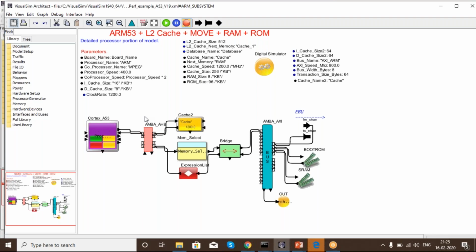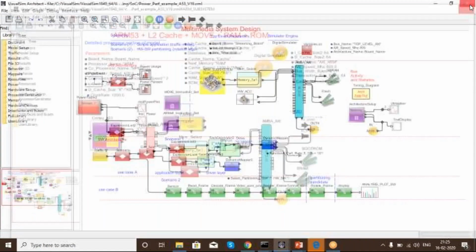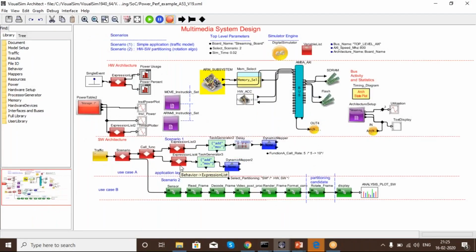So it is like building your model incrementally, step by step, and saving each function as a class or hierarchical block. This way, you are testing small sections of your design before adding it to the top level, which will help you in reducing most of the bugs at the model completion or simulation stage. Also use the displays and debug statements while constructing the model to test accordingly.